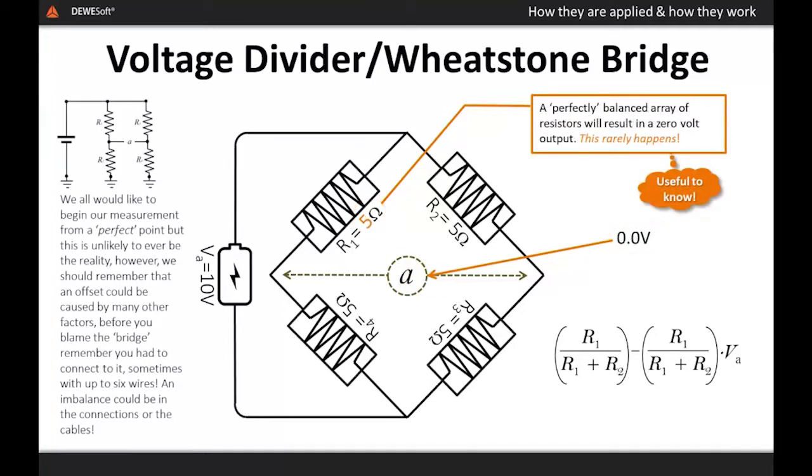In a perfectly balanced bridge, which of course we know is almost impossible to achieve without variable potentiometers or some other electrical mechanism, the measurement point represents as close to zero as it can. Like many measurements we make, we can use a process to manipulate that relative value to provide a second value for reference. We call this, in this case, shunting, and we'll look at that later. We can also take advantage of newer technologies to provide offset or imbalance compensations mathematically in real time.